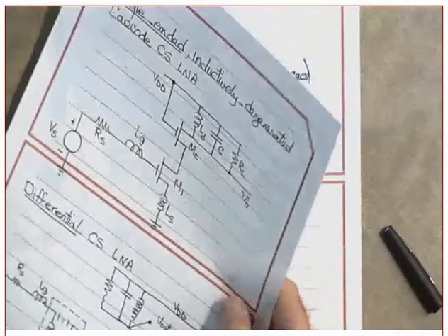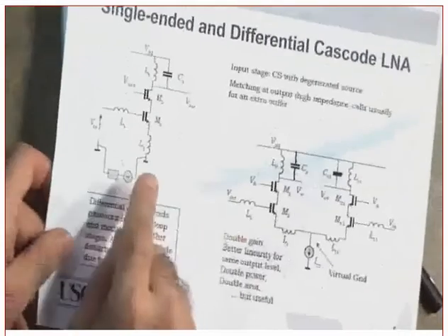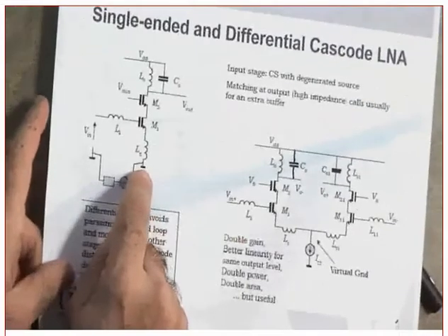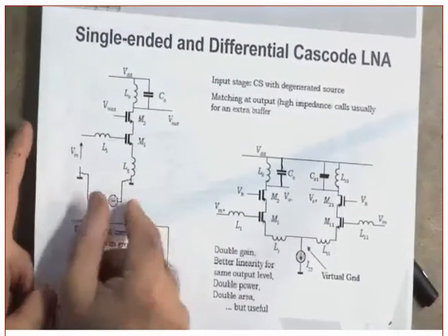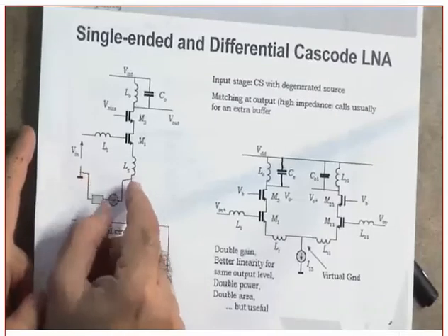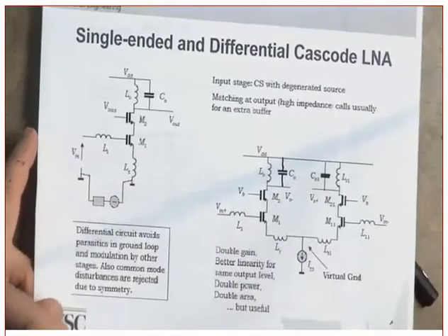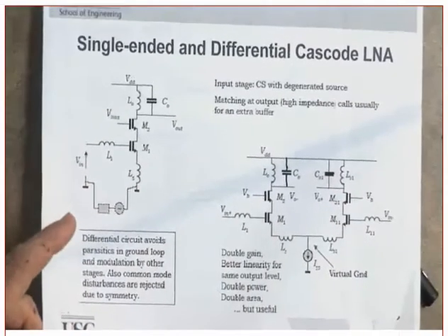Okay. Another issue, by the way, that you also need to take care of is the following. When you connect this one to the ground and you connect this one also to the ground, you need to understand that there's a possibility that this ground and this ground are not the same value. Did you understand what I just said or not?